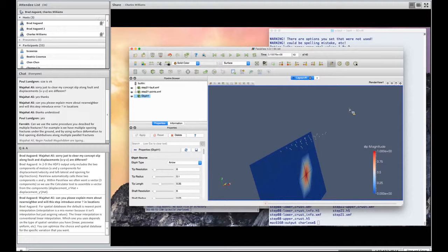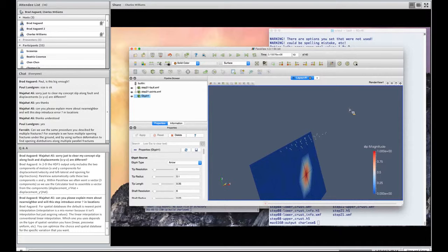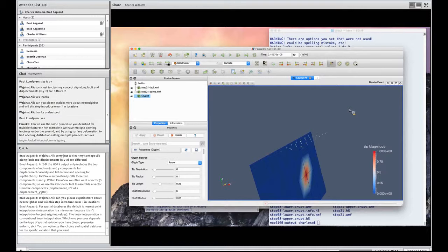Okay. Then get an output displacement vector along the line of sight. You would have to do that in post-processing. This would be like you would have for, say, InSAR or something, I'm guessing, or maybe LiDAR. In that case, you could do it in ParaView, but I would think you'd be better off doing something with a little bit of Python code to just dot the displacement components onto your look vector.